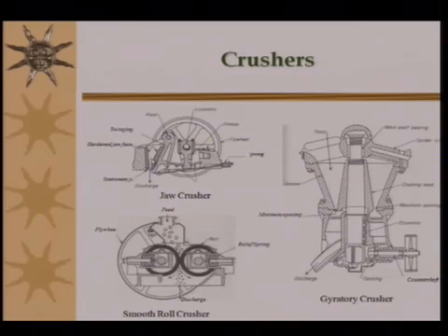Now here, this jaw which you see opens 250 to 400 times per minute in order to give a proper size of the product that you need. Also, the capacity of this kind of equipment is up to 1200 tons per hour, and it can reduce a size of 250 millimeter to up to 6 millimeter.